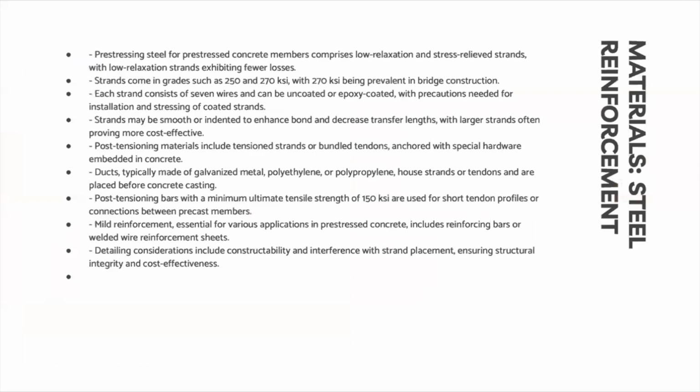So now we're going to talk about the steel reinforcement. The materials used in pre-stressed concrete members include pre-stressing steel, which is available in two main types: low relaxation and stress relieved strands.